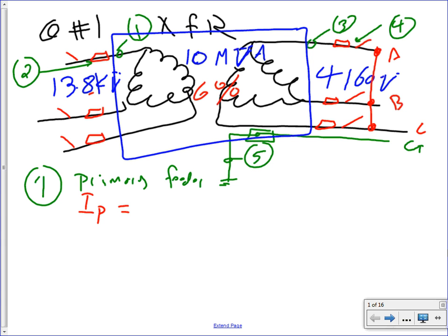You still need to provide a grounding electrode system. Where is the bonding jumper, Chad? Where's the bonding jumper here? No main bonding jumper because I don't have a grounded system. This is an ungrounded system. Can I have thumbs up that we understand why we don't have a main bonding jumper here? Because this system does not need a neutral. So I'm only pulling 4160.